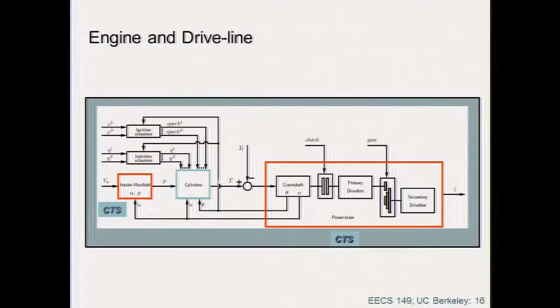But it could be positive, and why? Because as any dynamical system, right, any dynamical system, there is delays, right? So there are things that occur that need time to develop, right? So the combustion process is a physical process. It does take time, right, to ignite. I mean, we're talking about time in the order of milliseconds, but it does take time. So if I give the spark just at the right moment, I actually maximize, because I start the combustion process already. So when I'm at the topmost, I actually get the maximum expansion in the shortest possible time, because I already started generating this nonlinear phenomenon that is the ignition, right?